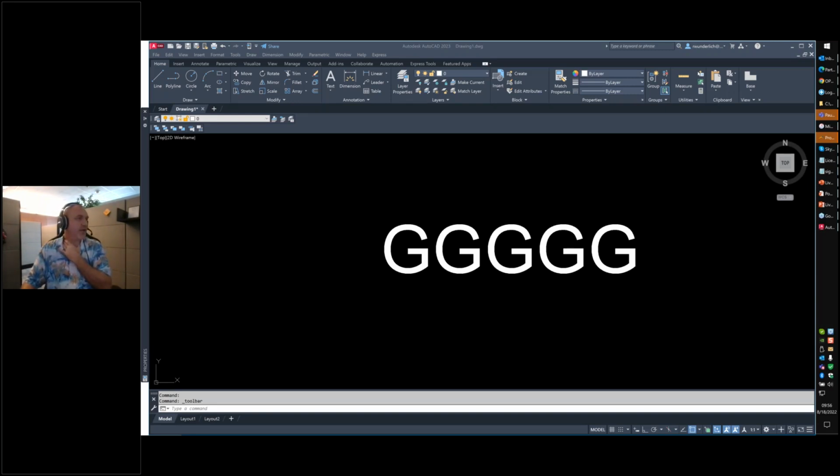Missing tool space after changing workspace in Civil 3D. So you're missing the tool space button. When you're in Civil 3D and your tool space disappears after you change a workspace, so you probably changed it to either planning and analysis or drafting and annotation or 3D, and then you go back to the Civil 3D one and it's missing. That might be something that we would have to look at updates. Depending on what version you're on, you may be missing an update for that. I know that there were some problems with tool space in Civil 3D 2022 that have been corrected. The other thing is you may have a corrupt profile. What I would typically do at that point is reset your settings back to the default in Civil 3D and see if the behavior continues.